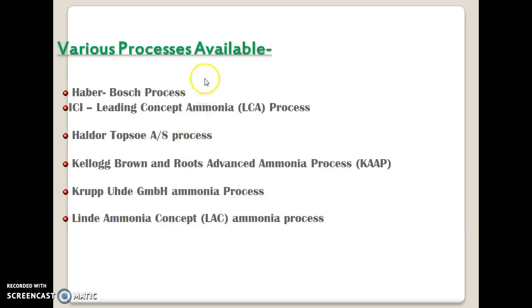With the increasing development of ammonia production, there is an improvement in the catalyst. People are trying different types of catalyst which can produce ammonia at lower temperature and lower pressure. The last, the Linde process, proposed 100 degrees centigrade and around 10 to 20 bar, contrary to 250 bar and 400 degrees centigrade in Haber-Bosch.